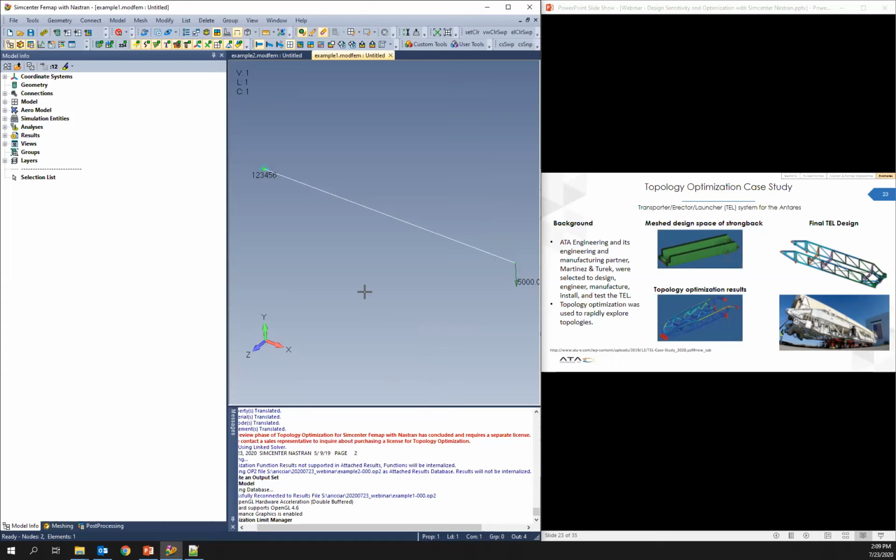You would have to double check that in what gets written out of Femap to make sure you understand what quantity it's writing for that response. I would be double checking that if you're running into that situation. But the ones today, it said weight, but it was mass.